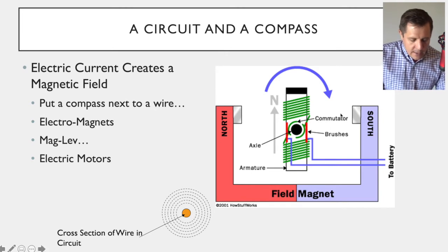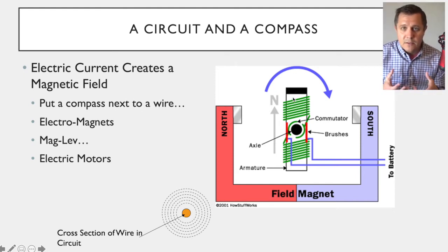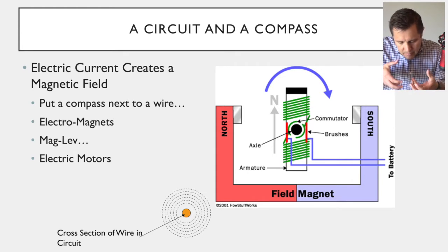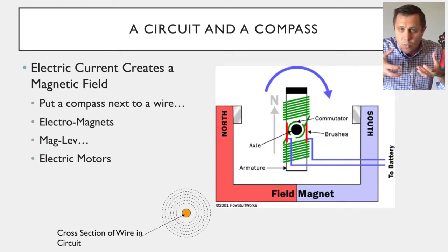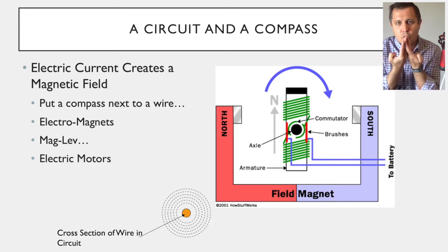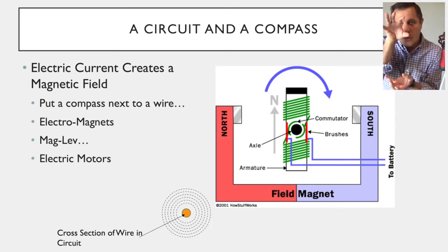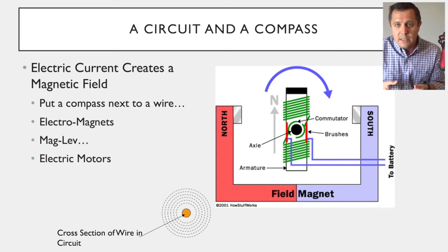So if you look at what a motor is, it is a bunch of wire wrapped around a magnet, okay, or a piece of metal. And then you'll have an electric magnet or electromagnet, and then you're going to have outside of it a solid state magnet. So what happens when the current runs through? When the current runs through the coils, the current's going to create a magnetic field, and because it's coiled up, it's even easier, where the current is going to start directing itself through that coil and be strong on one side to be north and strong on the other side to be south.